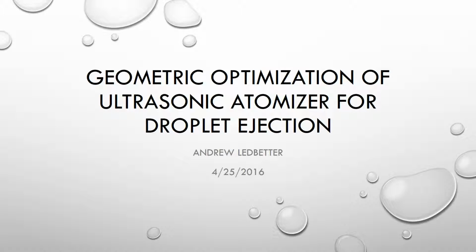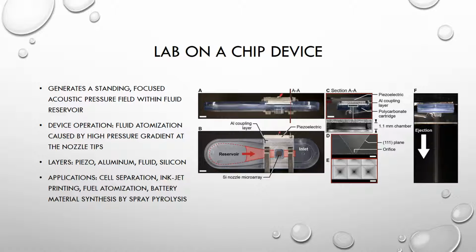My name is Andrew Ledbetter, and my project involved optimizing an ultrasonic atomizer for droplet ejection. The device is shown at the right and consists of a microfluidic channel that flows between a silicon chip with a microarray of pyramid-shaped nozzles and a vibrating aluminum surface actuated by a piezoelectric transducer. A focused acoustic resonance develops within the microfluidic channel with a well-defined time-averaged acoustic pressure field.